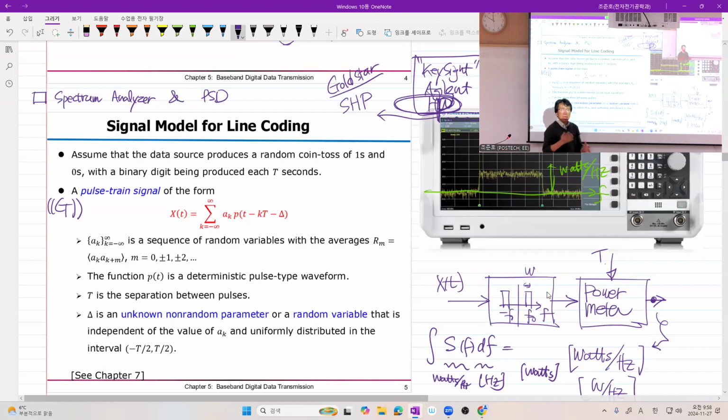Because most of the analog components are now replaced by digital components. So the measurement equipment itself has a very fast analog to digital converter, very accurate and highly calibrated, so the calibration error is minimized. And then they sample the signal, store it, and compute the power spectral density mathematically. They no longer use a power meter. So a significant change has happened.